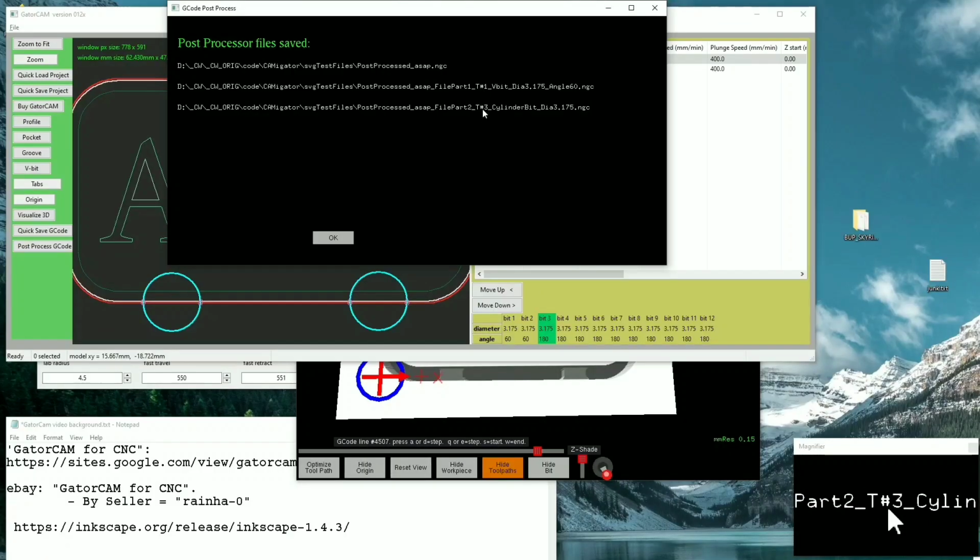Now, if you don't have an automatic tool changer, which I don't, it allows you to run the first file with your G-code sender, and then it will stop, and then you put in your new tool bit, zero that tool bit out and run the next file, and that way you have the 2 bits separated. And it's very intelligent the way it saves.